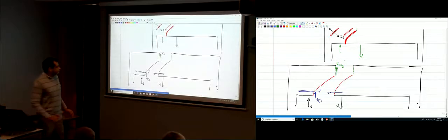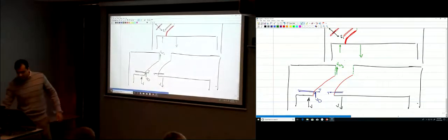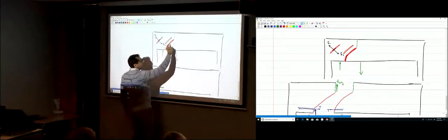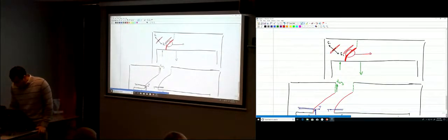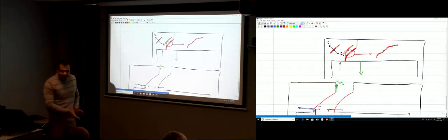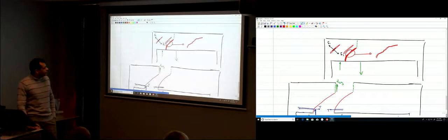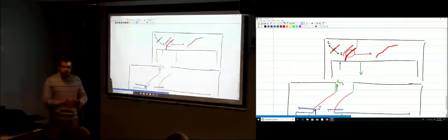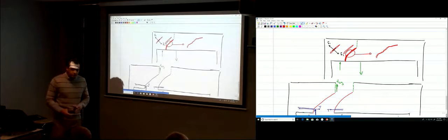And then along this red surface, okay, this red surface is what we have here. If we just enlarge this part here, it would look maybe something like this. It's not going to be a straight line. It's a crack that is corrugated a little bit, right? Why would it be corrugated like this? Because concrete is a non-homogeneous material. You have aggregates, right? So it's just going to go around those aggregates, right?